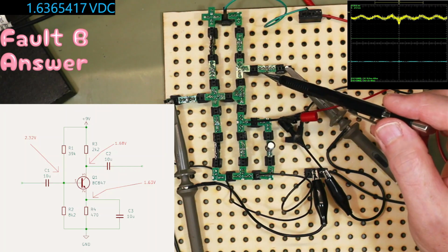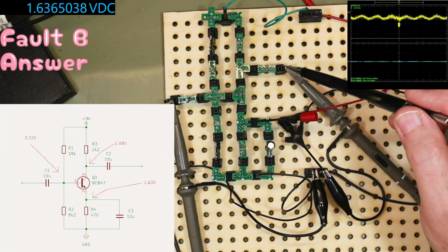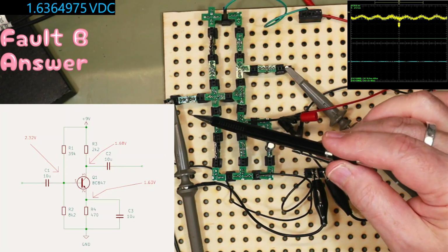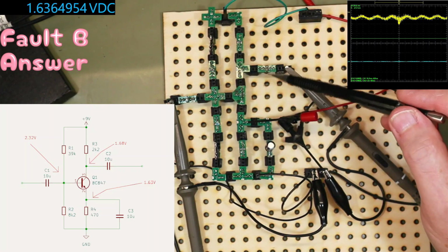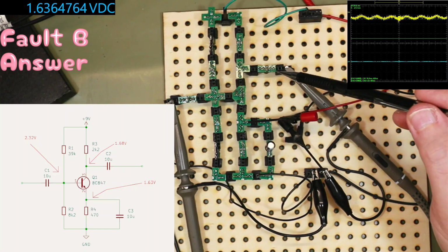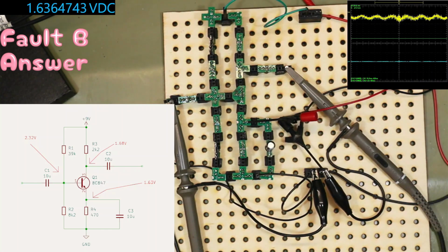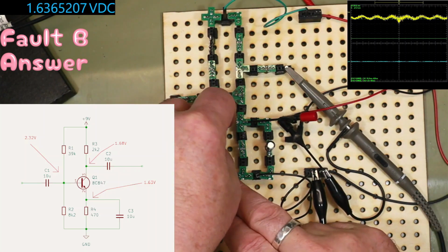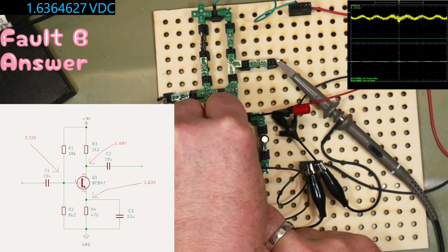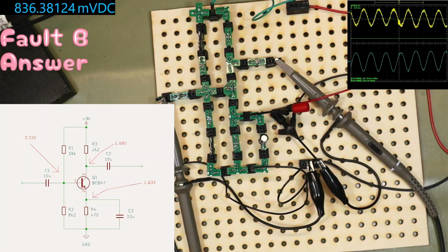The output will be heavily distorted. So we can see here the output has gone. If you drive a harder signal in, you might affect the base biasing conditions. So you might get a bit of a signal out, but the negative part of the signal is going to be heavily clipped. And just again to show that it is in fact the bottom resistor, I'll put this link back where it should be and give it time. It will all come back to normal.